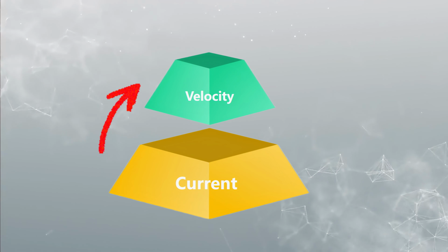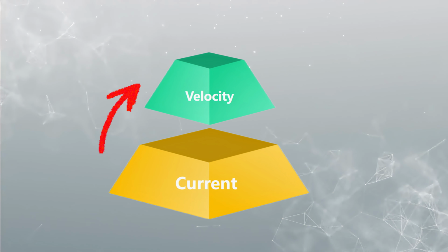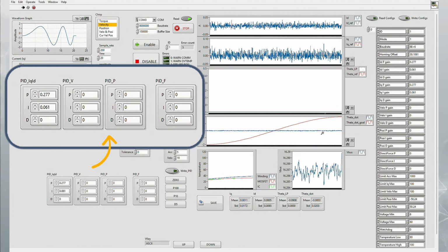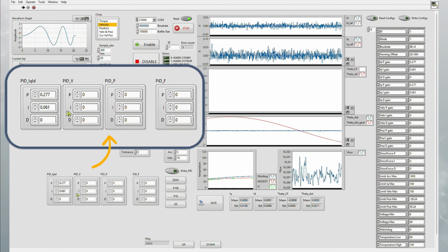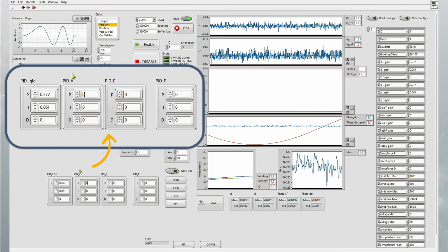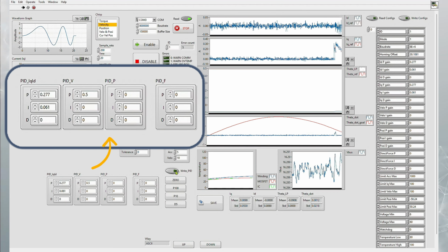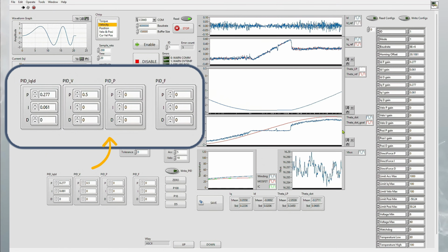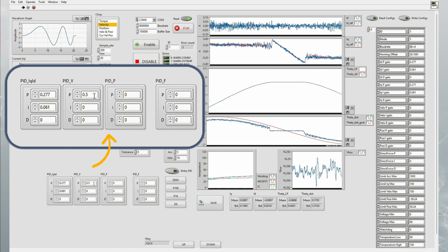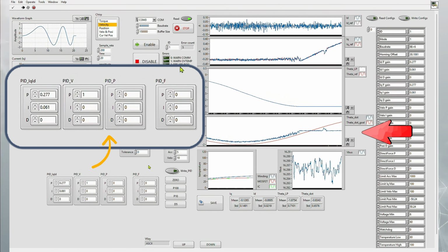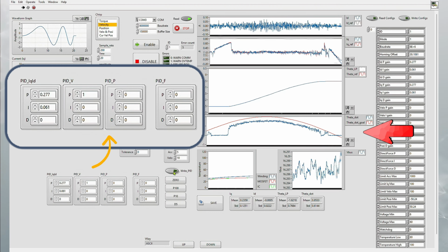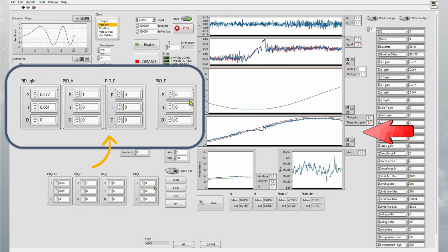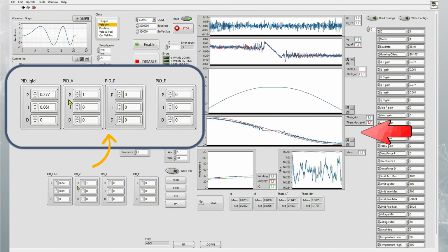Here, the velocity loop output feeds directly into the current loop, meaning you have 2 loops running concurrently. For velocity mode, the baseline parameters, setting velocity P between 0.5 and 1, I to 0, and D to 0, are initial testing benchmarks to ensure safe power-up. In real-world engineering setups, you must dynamically adjust these gains by monitoring whether the present velocity is actively catching up with the goal velocity on your oscilloscope.